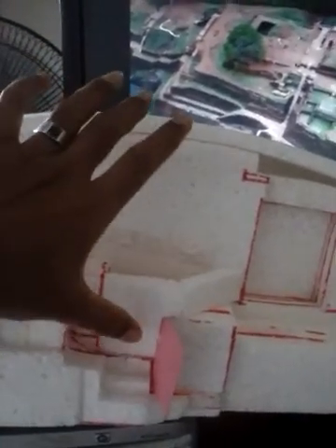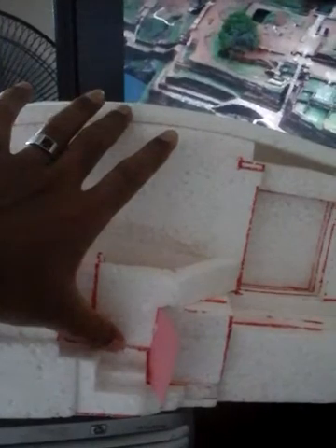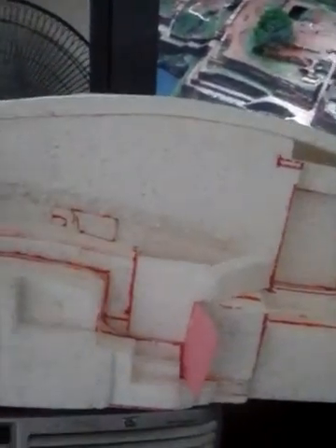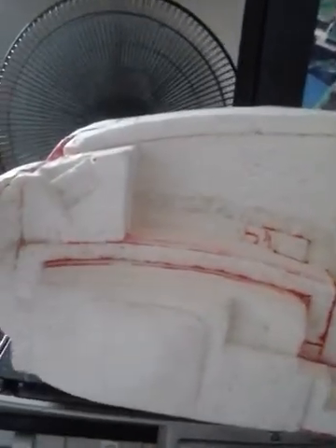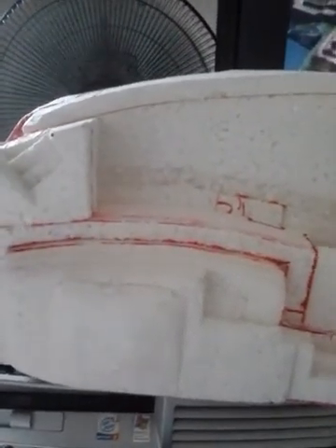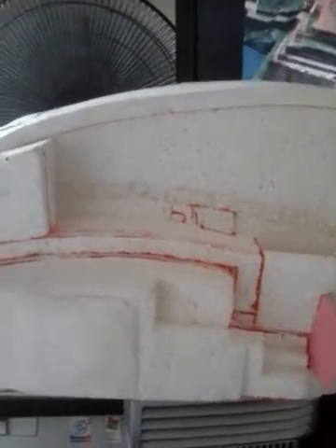But with the increase of the thickness, that also increases the resistance area of the wing. Therefore, it produces a high coefficient of drag. That is a disadvantage, because when the drag force becomes higher, that requires external or additional force in order to push the wing forward.